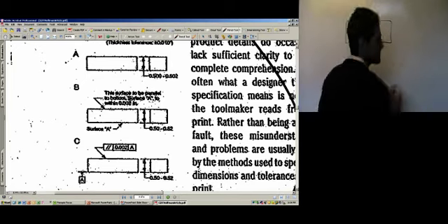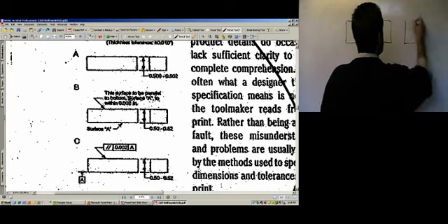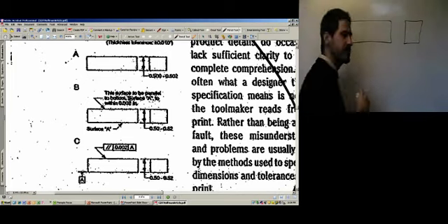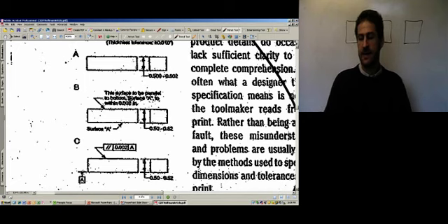It's just, I think it's a square cross-section, 1/2 inch by 1/2 inch. And there's two ways we can think about dimensioning this part. Really, it's in the drawing there, it's type A or type C. B is just kind of an intermediate. It's the same as A with some notes on it.